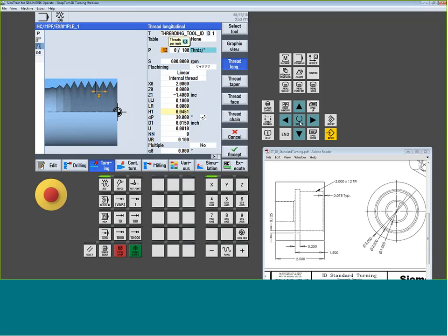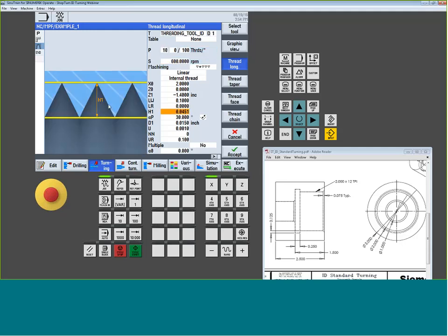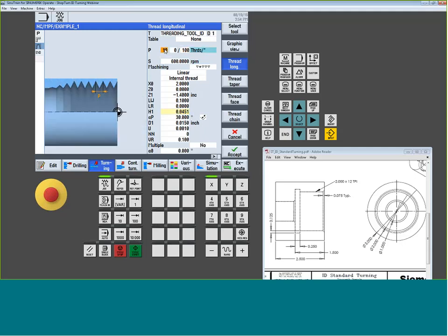Now, what's important here to keep track of, and later it comes into play, is the thread height. Unfortunately, we don't auto-calculate in inch threads. So if you watch, see how I have a value of 450 here. If I type in a value of 10, my thread height didn't change. Right? Thread height is the depth. But we do auto-calculate in metric.